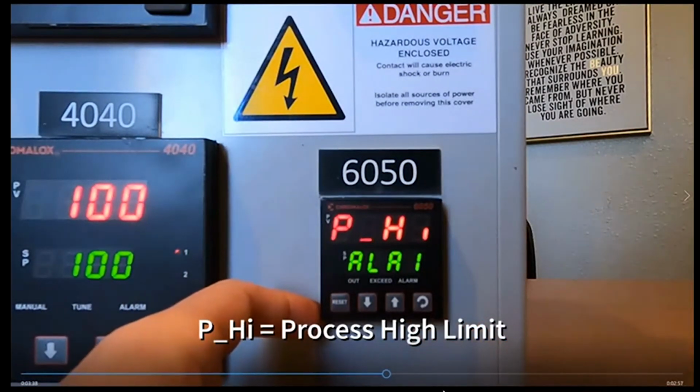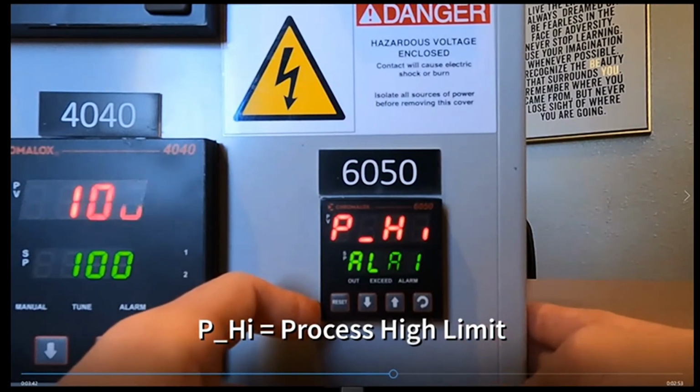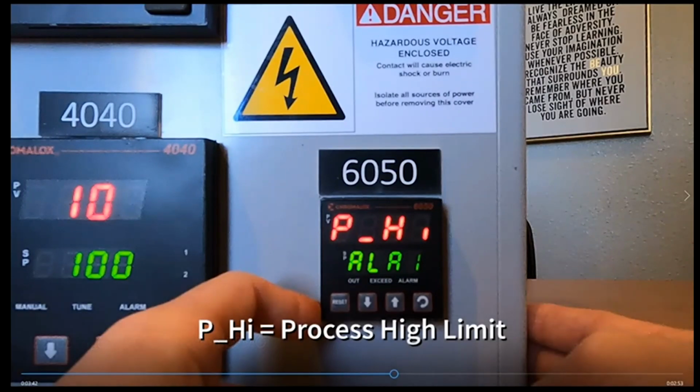Type of alarm. Yep. Okay, actually, I want to pause real quick here. You might want your alarm to be a lower value than your actual set point for these high limit controllers. If somebody is on site looking at the application, that might give them time to fix something before the actual high limit has been reached, if that makes sense.